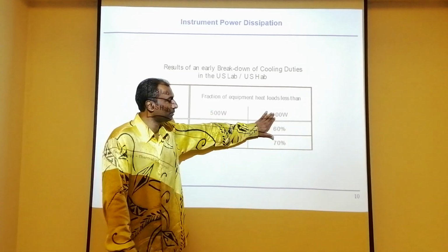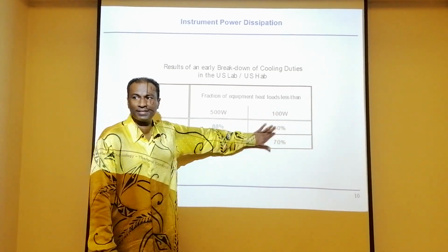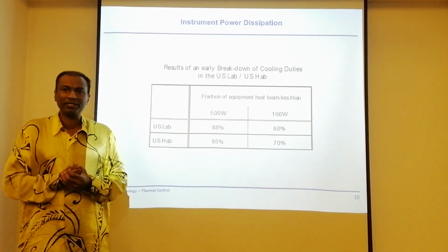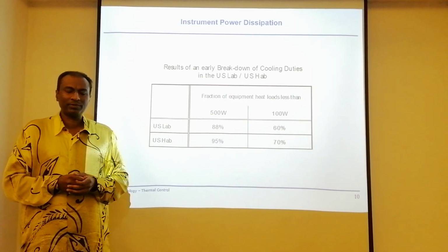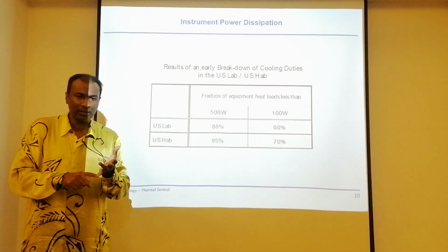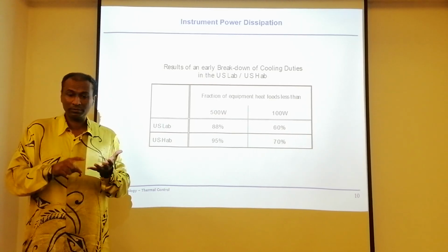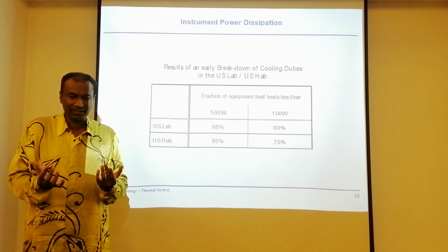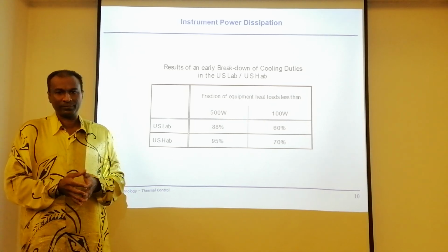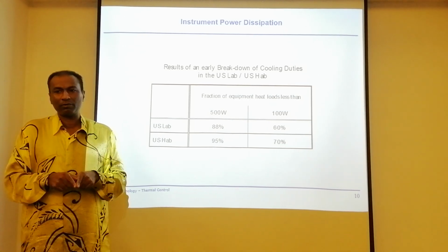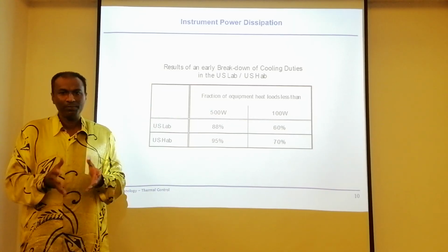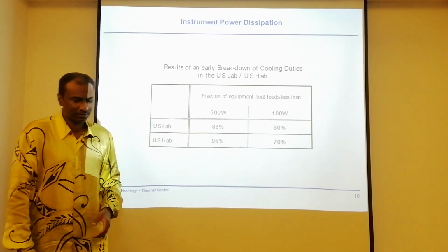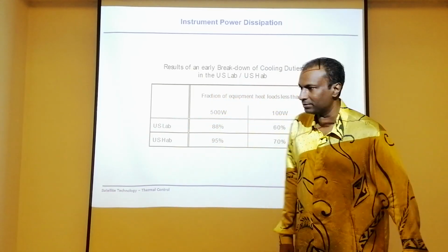So if you have a low power consumption, you have lesser heat generation. So in a way, now when you want to procure a satellite, you want to go for low power consumption. Therefore, it is going to be a low power dissipation. So dissipation is low, so you will not burden your thermal control system. That's important. But if you put a human on board, you can't run away. You'll fall in this category. You have a lot of equipment to maintain the human's comfort zone in space.